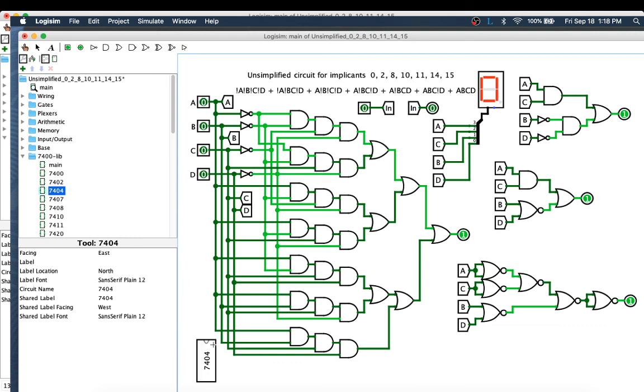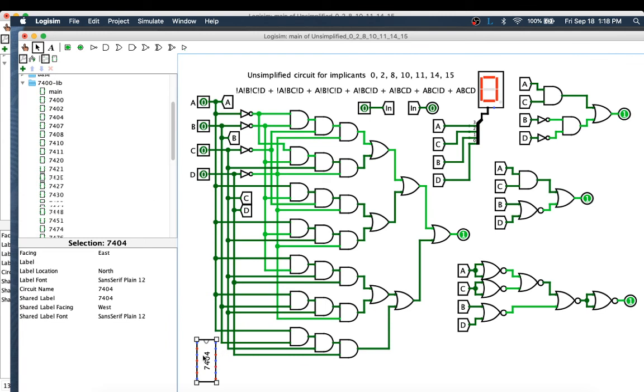That's a quad 2 input AND gate. So it's got 4 AND gates on it. So we're going to be using those soon. So I just wanted to show you how to load the library. And you can look up under datasheetcatalog.com, you can look up the pinout for that. Oh, this is a 7404. That's an inverter. Sorry, that's not a quad 2 input AND. I thought I grabbed the 08. It's the 04. So that's a 7404 inverter. So this has 6 inverters in it on this chip. So anyways, that's good enough for now.